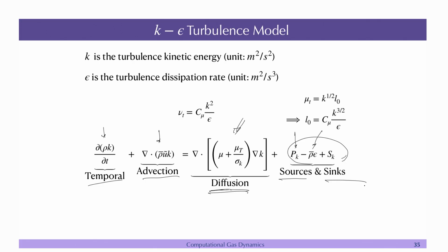Okay. It is not derived completely from first principles, although you can take the momentum equation and subtract the mean. Basically, you can take the turbulence kinetic energy equation, dk/dt, and subtract the mean turbulence kinetic energy, and you get this equation in terms of k, but then you have some more terms being added here. So this cannot be derived directly from first principles.